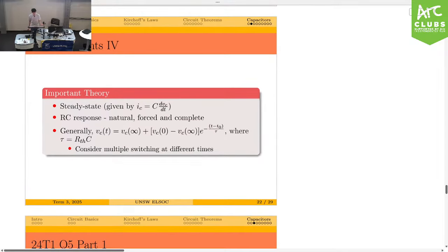So here's a bit of theory. I'm not going to go too deep into it. Hopefully you guys know the theory. I'll just go into the questions. The 2 things to keep in mind are sort of this differential equation that describes the behavior of capacitors, right? So they're related by the change. So the current going through the capacitor is related to the voltage across it. Because of the passive sign convention, we say that this is IC going down, assuming that this is VC.